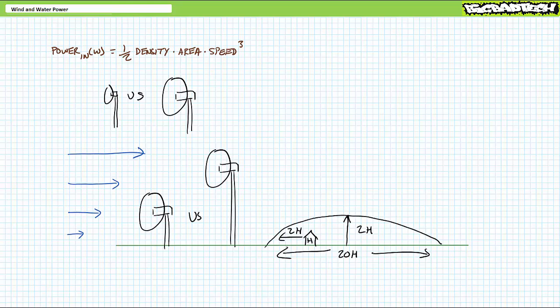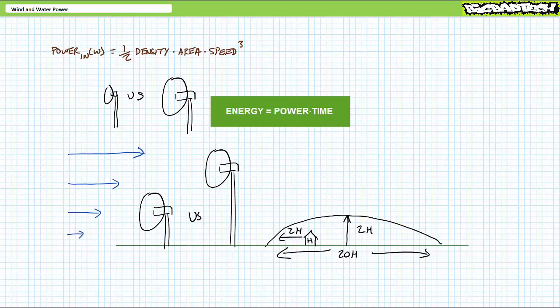Before I address the final question, I should note that although wind speed is the single most influential factor in determining instantaneous power output for a turbine, far more importance needs to be placed on average wind speed rather than some peak wind speed for a particular location. Wind turbines, after all, are in the business of making energy, and energy is power times time. This means a turbine installed in a low wind environment that regularly experiences low wind on a nearly continuous basis, even if it's the low end of the operational range of a particular turbine, might actually produce more energy than would a single larger, more powerful turbine operated at the rated speed only on occasion.